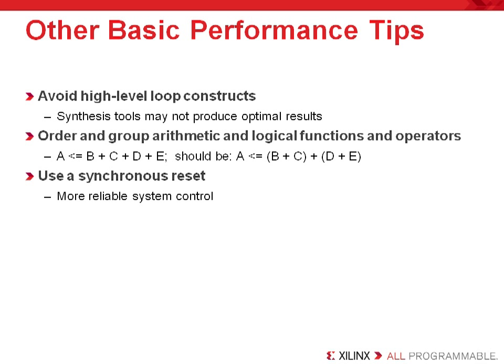Recall that the carry logic resource will program each LUT to do the addition of 2 bits plus the carry input. This is also important for logical functions. Finally, use synchronous resets whenever possible. Not only is this good for circuit reliability in all FPGAs, but it enables efficient mapping to the FPGA architecture.